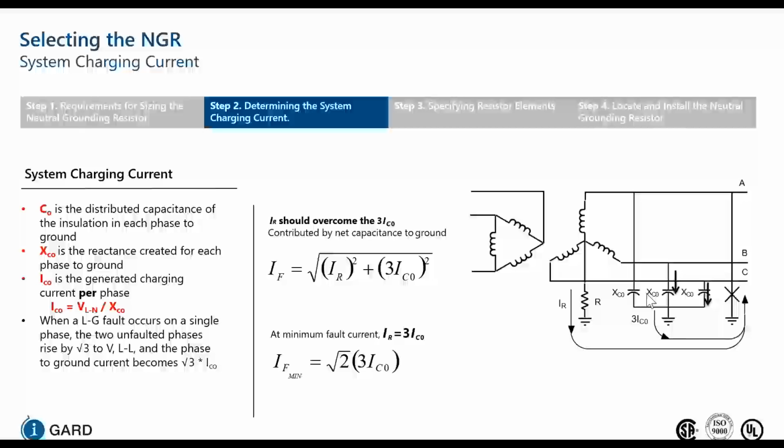On an ungrounded system, because there is no resistive charging current, there is no limit when you have intermittent arcing faults in your ground network or in your network. And most of the time you're going to have intermittent arcing faults, repeatable, in a motor. So your escalation of voltages becomes unpredictable.